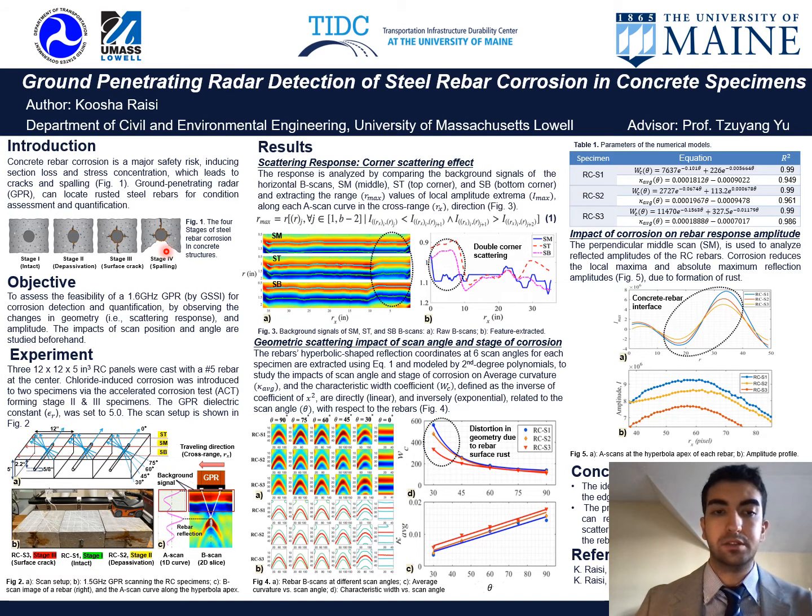And it will be very costly to repair these, because as you can see from stage 2 to stage 3, visually we cannot see anything. So we need non-destructive testing methods in structural health monitoring, so we can monitor and identify these issues, specifically corrosion issues, before they reach a critical point, and they can cause safety hazards on top of that due to sudden failure of the structures.